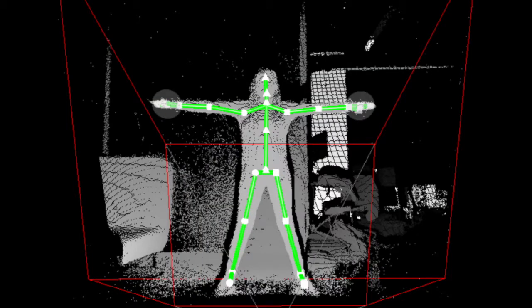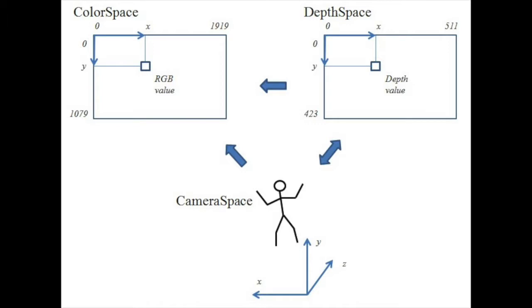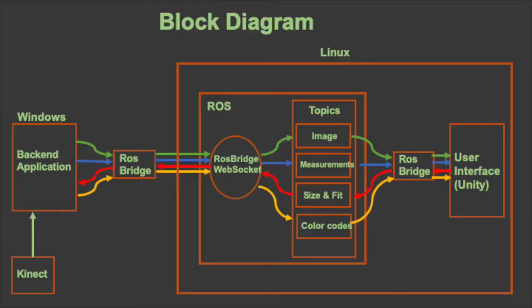The idea here is to use various joint coordinates obtained from the skeletal data and find useful reference points to mark the locations required for all the computation in the process. The Kinect SDK uses color and depth sensor data to offer 3 different coordinate systems: camera space, depth space, and color space. The joint locations are read in the camera space, which are the real-world coordinate points in the camera's frame of reference. We map these coordinates from camera space to depth and color spaces, perform the vital computations, and then reverse map to calculate real lengths of the minor and major axis in centimeters.